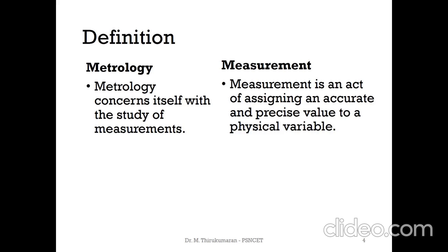Next, measurement. So what is a measurement? Measurement is defined as the process of numerical evaluation of dimensions, or otherwise the process of comparison with standard measuring instruments. The basic aim of measurement in industries is to check whether a component has been manufactured to the requirements of the specifications or not. The elements of measuring systems include the instrumentation, calibration standards, environmental influence, human operator limitations and features of the workplace.